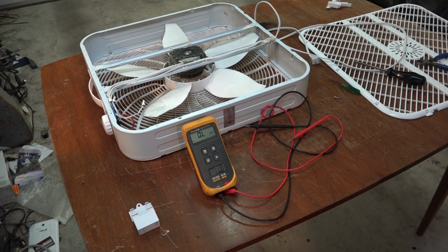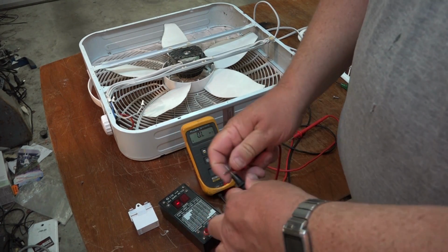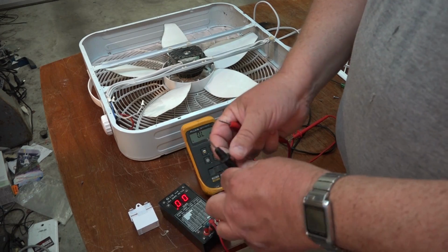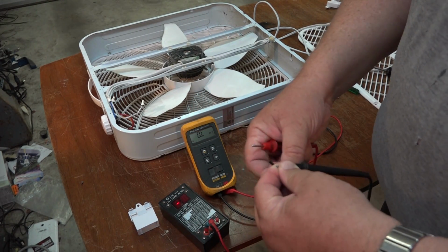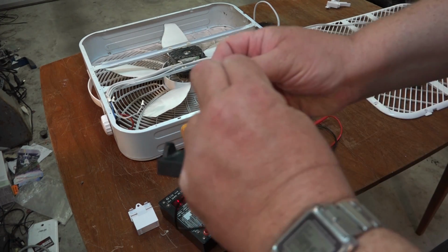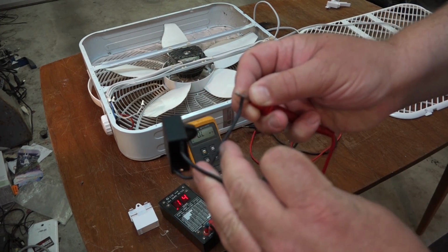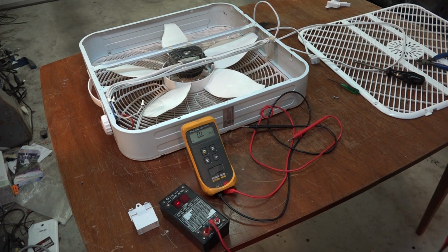For the heck of it, let's just see what the ESR meter shows on this thing. So I've got my ESR meter. We'll zero it out, and we'll just measure with the ESR meter. There you go, 0.14. So it will pass. The ESR meter will pass it. For the hell of it, I'll just grab the other old capacitor and we'll measure that with the ESR meter as well.